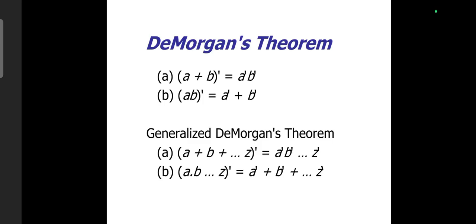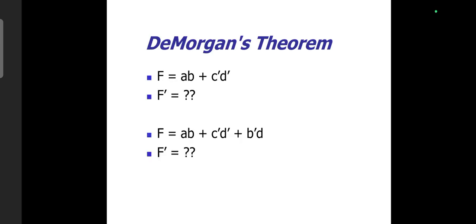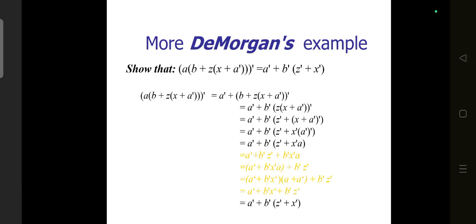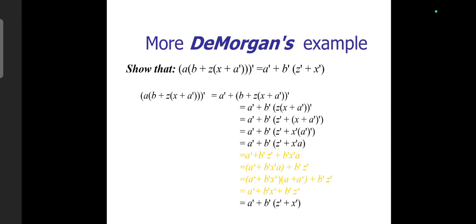So now let us discuss why this kind of functional minimization is such an important topic in digital design. Imagine that two engineers are asked to build exactly the same logical function. The first engineer implements the expression directly without simplification and uses 10 logic gates. The second engineer applies Boolean algebra and reduces the expression before implementation. As a result, only 5 gates are required. Both circuits can produce the same output, but the second circuit is clearly superior.